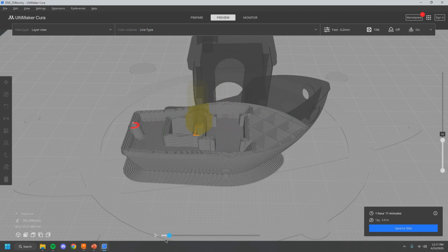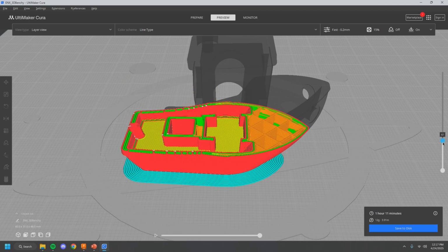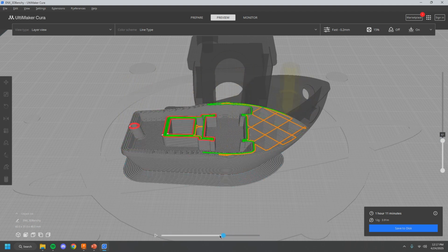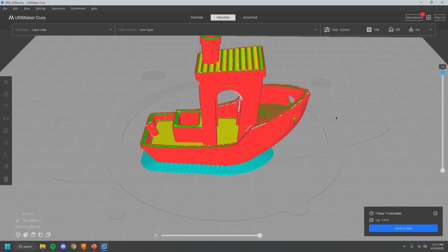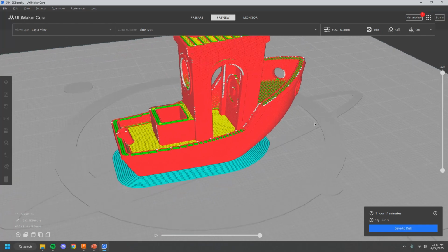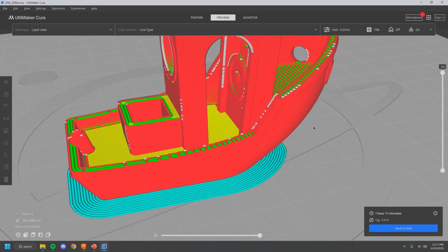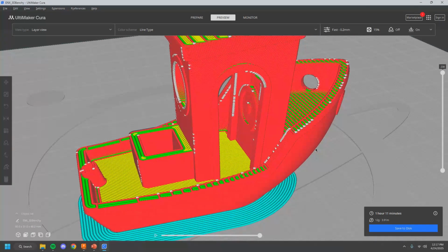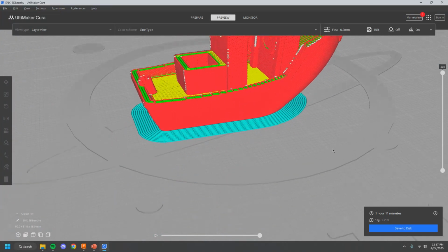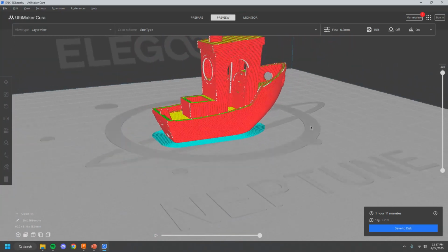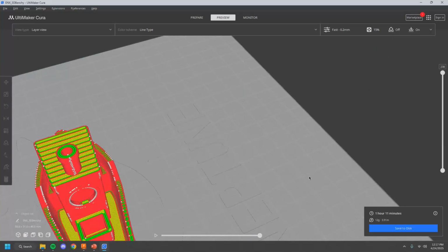You can see that's what it'll look like on this one layer. If I go down one level, you can see that's how it's going to fill in this layer. Essentially, this software is turning your 3D model into instructions for a 3D printer on where to extrude, how much to extrude, and how fast to be moving to actually get it into a 3D model. So a very simple display for the students.